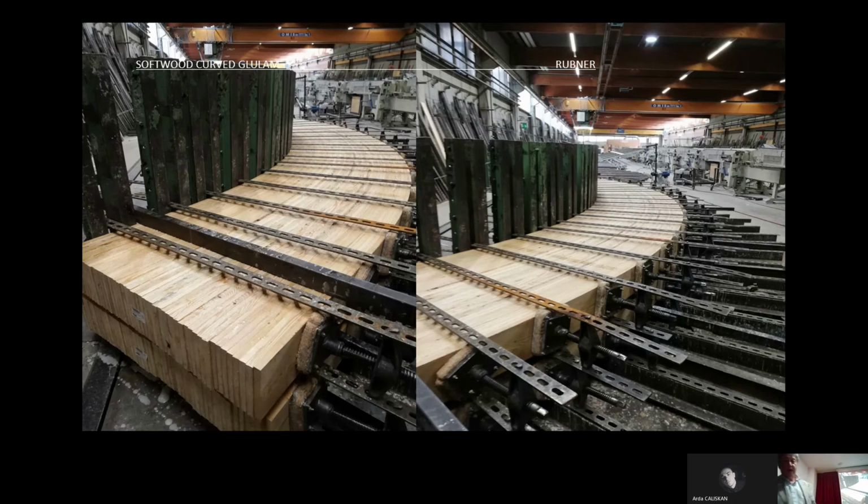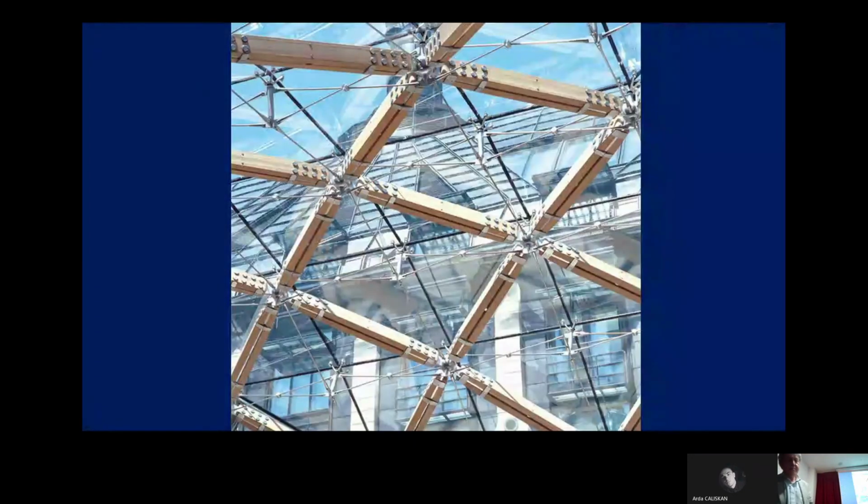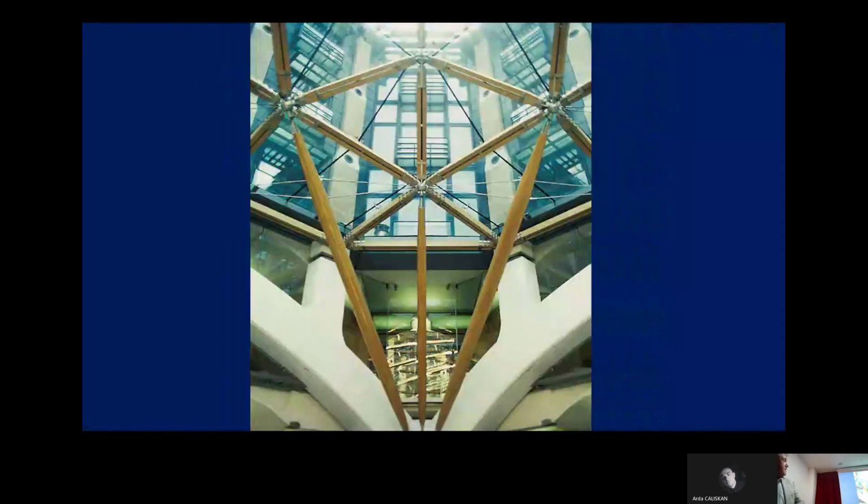This was up in Rubina, up in the top of Italy, up near the Alps. Go back to Portcullis House, which was the pioneer project for us, really, that first opened our eyes, as I talked about at the beginning of the presentation, in laminated white oak. And also a slightly different dimension, the cigar-shaped tubular columns, again laminated in white oak and turned on a big lathe to form the initial support structure for that roof.